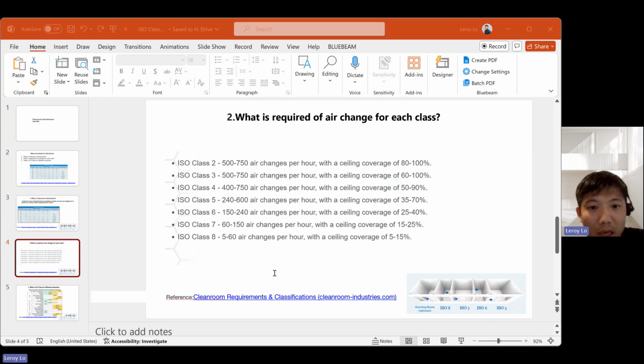And you know what that means? You don't have any space. You have to have a special ceiling system to accommodate lighting, because you need the light integrated into the ceiling system or suspended from below. Those are things you need to think about. Also, these filters become extremely heavy, so with modular clean room ceilings, you sometimes need stick-built ceiling systems.